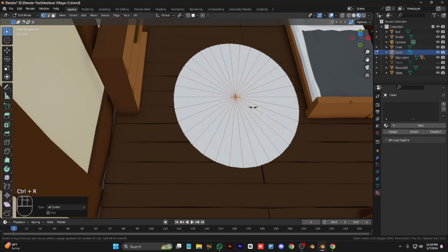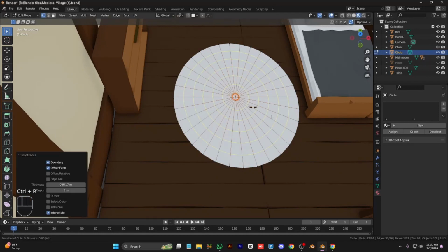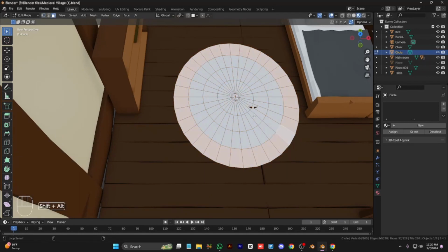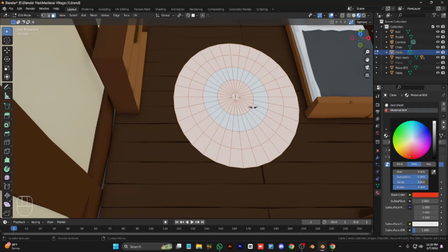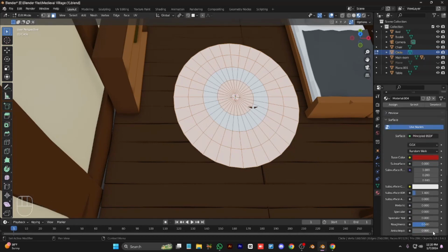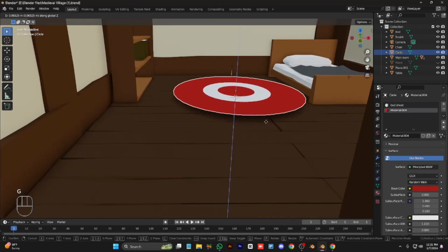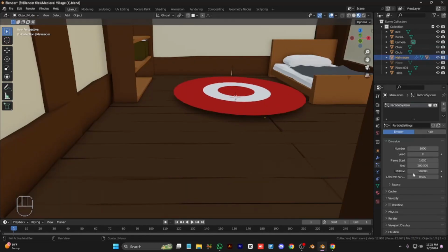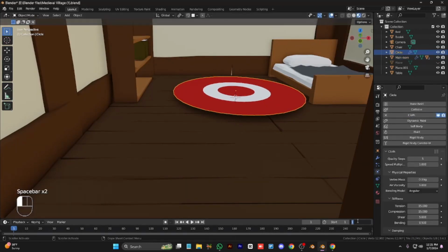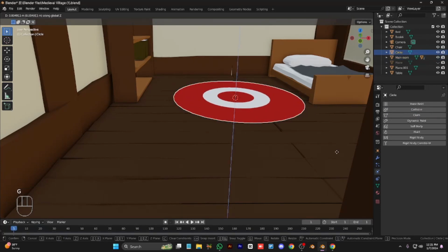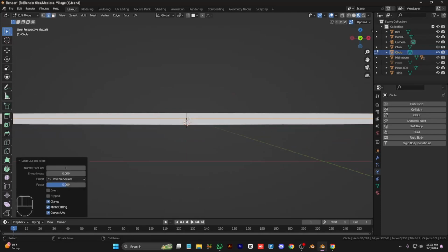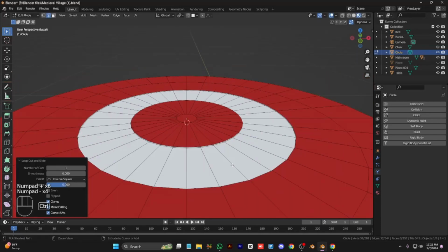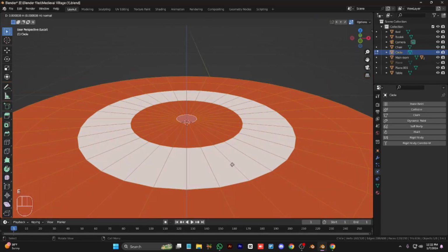adding a circle and inserting it like that, and add 2 to 3 loop cuts right there and color them the color you like. I will color it a little red and the middle one will be white. Middle loop will be white. I will bevel the side vertex and make it white and extrude it to make it a little thicker. Okay, nice.